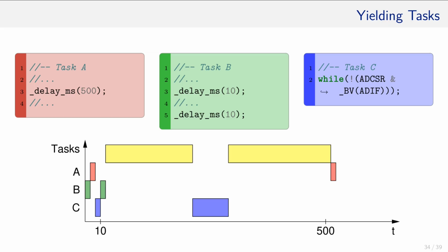Unfortunately, it's not that easy, since not all conditions for tasks are wake-up conditions while the MCU sleeps. In addition, how will the scheduler know how much time is 500 milliseconds or 10 milliseconds? When the MCU sleeps, the time stands still as the CPU is not clocked anymore. While this is the ideal scenario, can we have a working scenario without much complexity and implementation efforts?